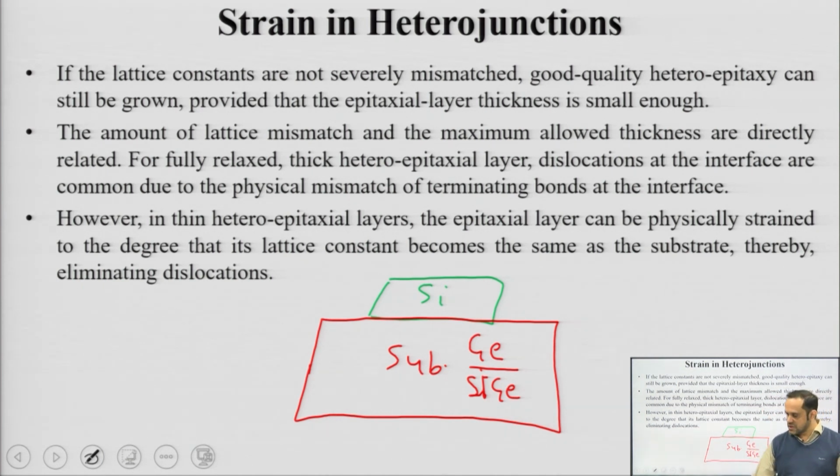This tensile strain alters the energy band diagram. It increases the energy band curvature, which reduces the effective mass and produces high mobility, as mobility is inversely related to effective mass. So, when effective mass reduces in strained devices, mobility goes up. This is how you can produce high mobility semiconducting devices.